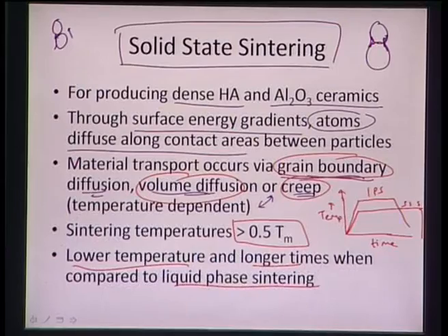One more difference is that if we have a liquid present in the material, it will tend to draw all the grains closer to itself, which leads to much more densification. So overall densities in solid state sintering are much lower as compared to liquid phase sintering. These are certain differences between solid state sintering and liquid phase sintering.